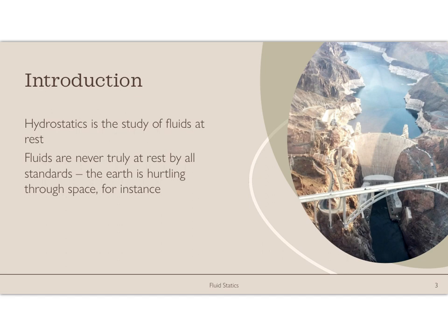By way of introduction, I'd like to define hydrostatics for you. Hydro, fluid; statics, at rest, or static, right? So we're studying fluids at rest. But we know that a fluid is never truly at rest, right? I mean, if the fluid is on Earth, it's moving through space. So what do we mean by at rest? In this case, we are saying that the inertia is zero relative to the Earth or whatever other frame of reference we are using. That means that you're only going to have pressure forces and gravitational forces.